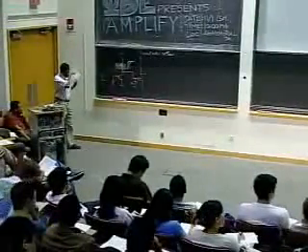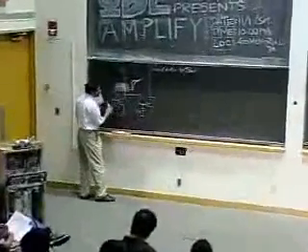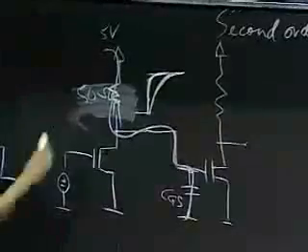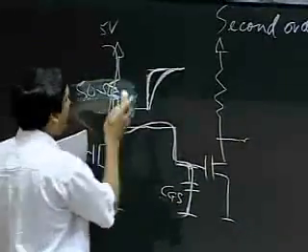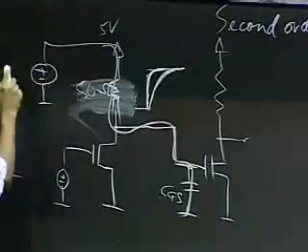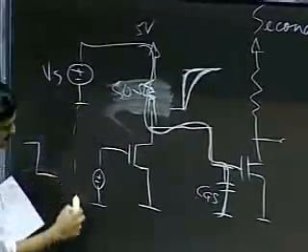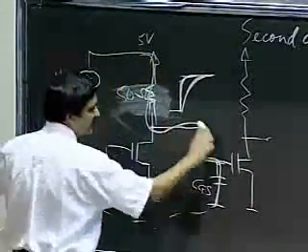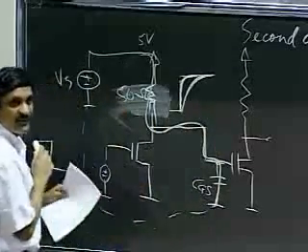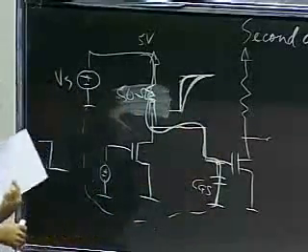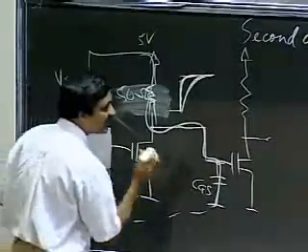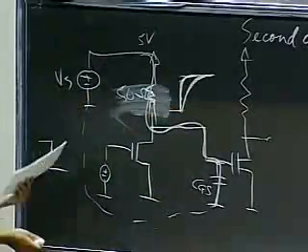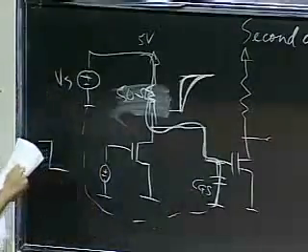So what's going on here? What's really going on here is, take a look at this circuit here. But take a look at this path here, okay? And this is your Vs voltage source. So the path kind of goes like this and around. Turns out that this circuit is a loop here, okay? And when there is current flow, going down to basic physics, you remember that the loop also encloses some amount of flux, so there's a current flowing in a loop, okay? And because of that, there is an effective inductance here.